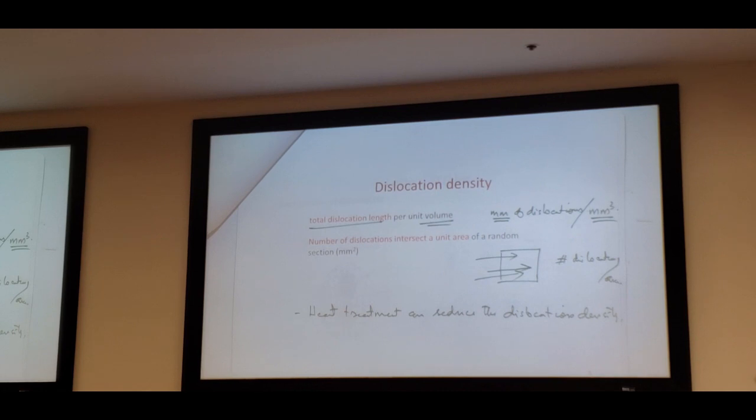If there are two dislocations, under normal conditions, room temperature, in order for a slip to happen, the dislocations should move. So if there is one dislocation at this point and another at this point, assume that under normal temperature, this cannot move. But as the temperature increases, what happens? Energy is higher. Remember, similar to that activation energy.